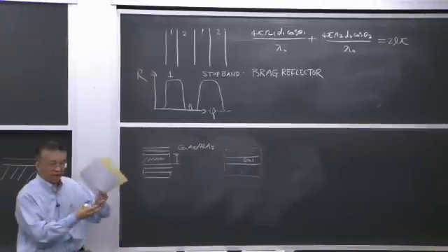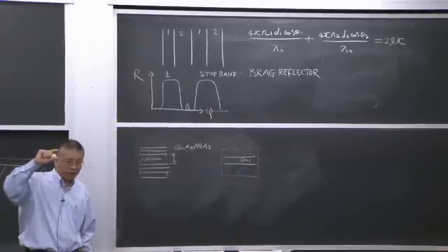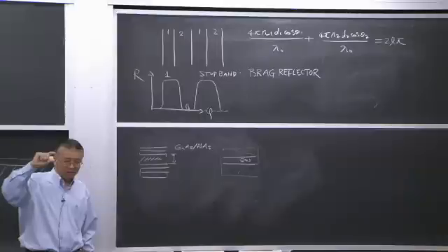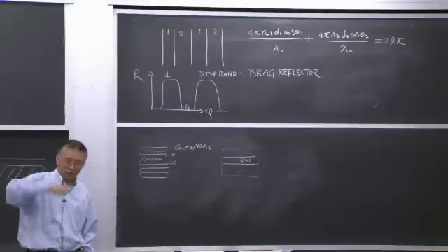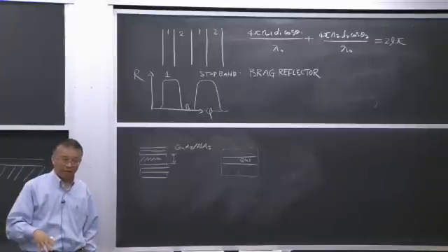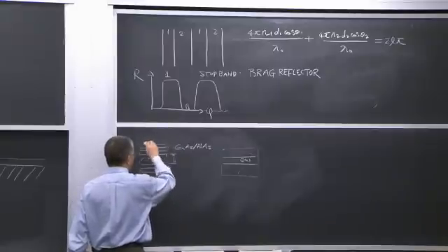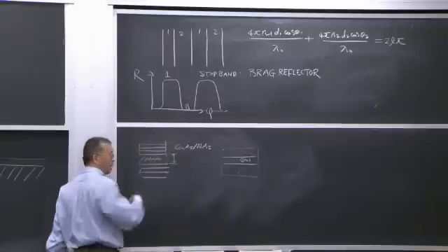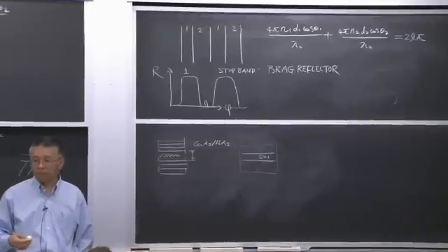Okay, so that's a cavity area. But the light only travels a very short distance, right? So in this case, you need multiple bounces. You need a high reflectivity so that the light is bounced back and forth and gets amplified. And to get that high reflectivity, they will deposit this Bragg reflector on the top and bottom, made of gallium arsenide and aluminum arsenide.